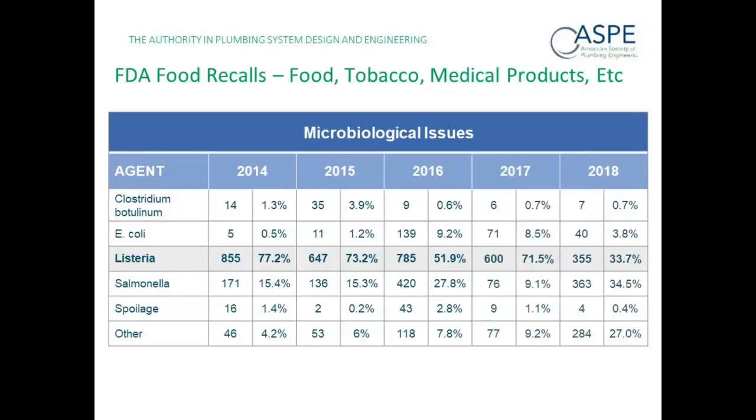The answer is yes, it can absolutely translocate through that methodology, because you are breeding the bacteria or pathogen in the drainage system. It gets up into the drain. Because we know that, once you put something down the drain, it doesn't go away. If you have high winds outside, I don't know how many of you have worked out in the field and you've heard a bubbling P-trap or you smelled hydrogen sulfide, whatever phenomenon occurs to actually dry out the drain trap, then that pathogen has a pathway to the facility. Oftentimes, drain cleaning, which we're going to cover, is one of the leading causes of translocation of the pathogen.